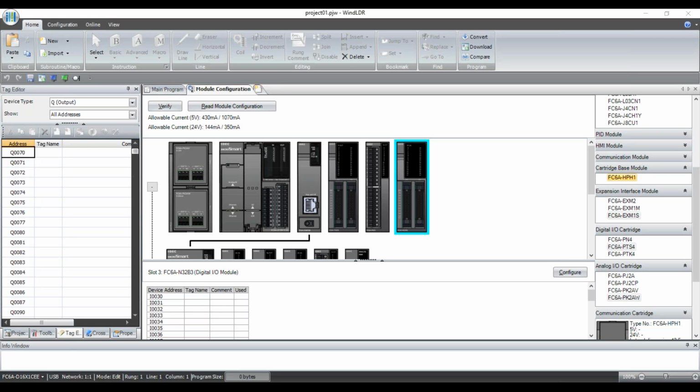And this isn't using expansion I/O. It's everything set up over Modbus. But it's pulling data back into the main PLC, and then that main PLC is pushing data from all the wellheads into a software package that they've got running back at their headquarters.